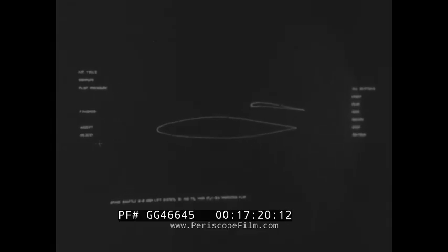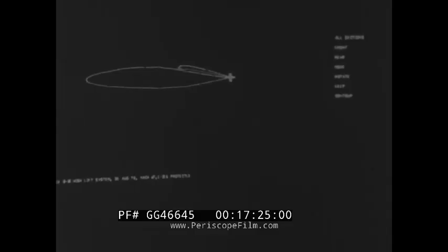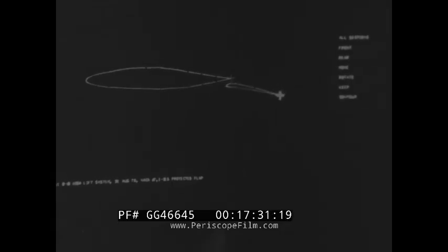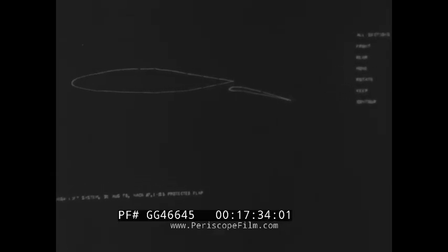The high-lift system geometry is stored on punched cards or magnetic disks and can be displayed to the operator upon command. We will see the Space Shuttle flap in partially deployed condition. The flap stows on top of the wing as a protective measure against high temperatures during re-entry. I can move the flap with my light pen. Let us move it back to simulate a track-mounted system, or a system attached to a 4-bar linkage.